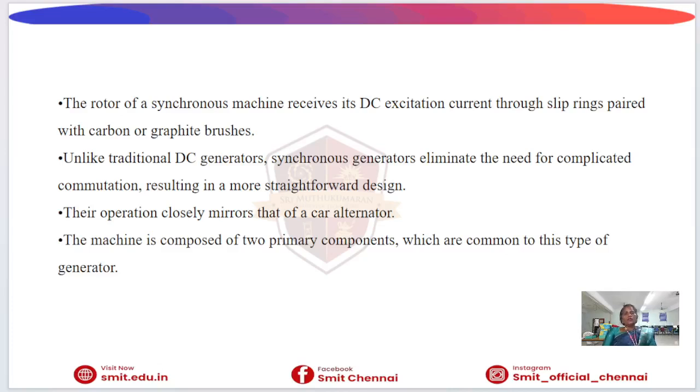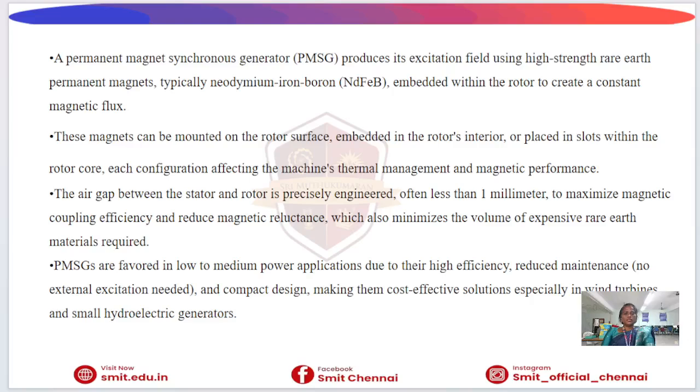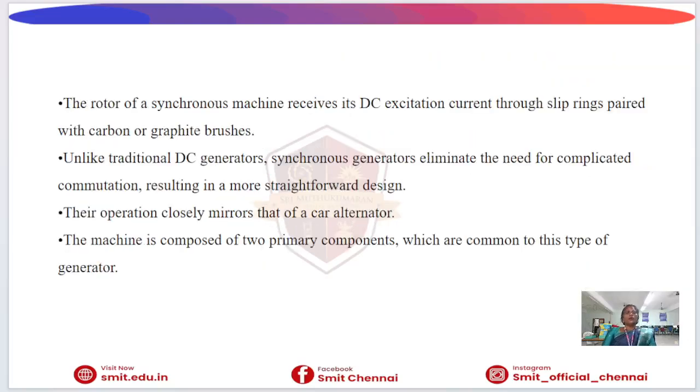In direct drive wind turbines, permanent magnet synchronous generators are widely preferred. These generators can have a large number of poles, sometimes more than 60 poles, allowing efficient operation at low rotational speeds. Since no external excitation system is needed, the overall system becomes simpler, more reliable, and more efficient. Another disadvantage is that the generator achieves maximum efficiency only at a specific wind speed because rotor flux remains constant.